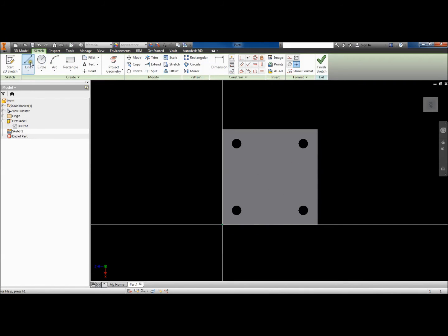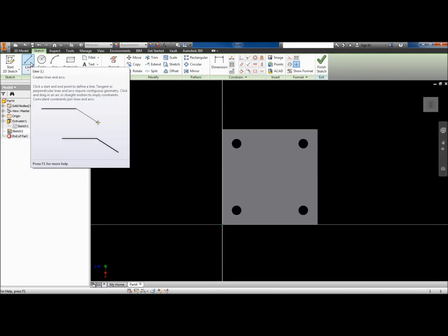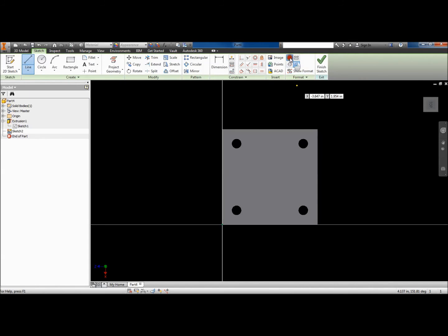And there are just a number of ways that we can do this. I can create a line, and then I can make it a construction line. And when it's green, remember, it's in the middle of the line, and I can pull this out, and I can hover in this position, and I can pull that back, and I can put that exactly right. Now I can kind of check that so that if it's at 90 degrees and it's green, I know that I'm exactly in the center of it. So at this point, I can turn off construction mode, and I can put my 2 circles in that I need to extrude. And so my first outer dimension is 1.5,